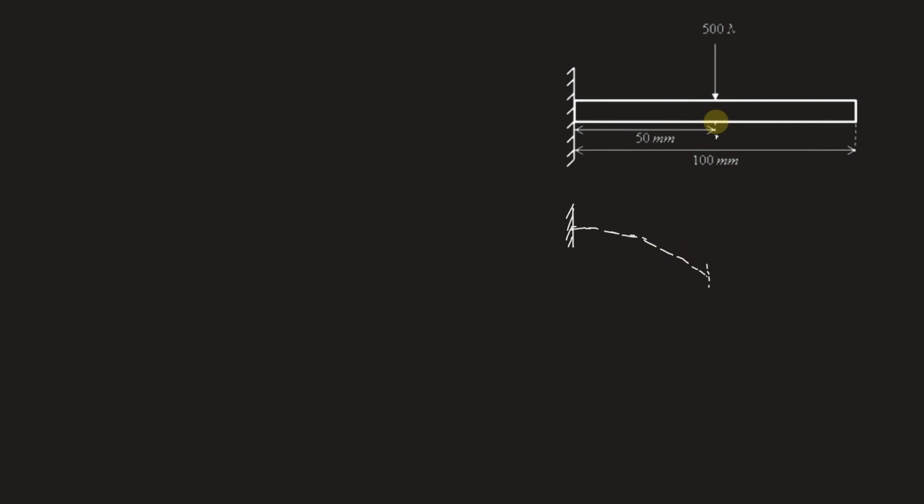So if we let this be point O and this be point C, till point O the beam is bending. This being the straight beam, at the fixed end we consider a point A. The curve AO shows the deflected curve between points A and O, while the deflection curve from O to C will be a straight line, because the beam is not going to deflect, but it is going to only rotate beyond point O.